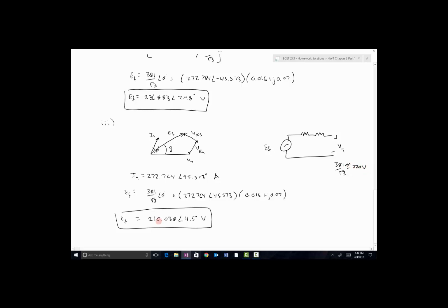So we see that for a leading power factor, the excitation voltage is actually lower than the terminal voltage due to the phasor mathematics, which is very interesting. Leading power factors, or positive Q's on the load, actually cause the terminal voltage to rise on a synchronous generator. Very interesting phenomenon that isn't immediately obvious, I think.